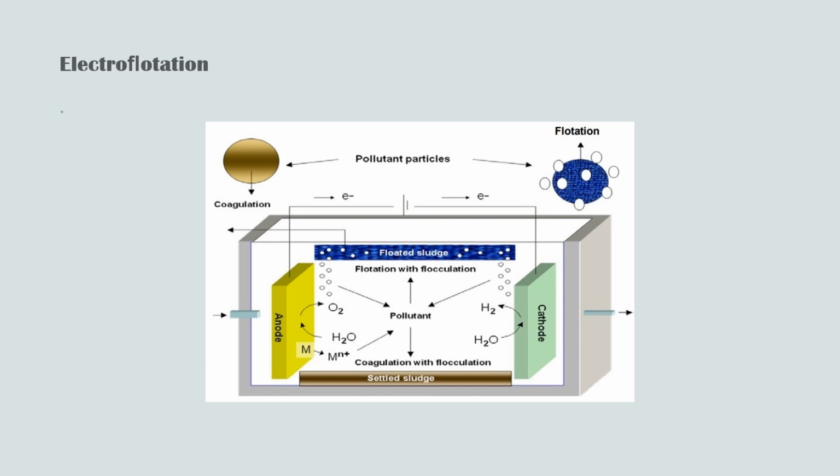In ordinary flotation, a gas, which may be air, is passed through the water to be purified. Its bubbles, while rising, carry along the surface active contaminants as well as colloidal or other suspended substances in the water. The finer the gas bubbles, the more efficient the flotation, and the contaminants float on the surface at an early stage.